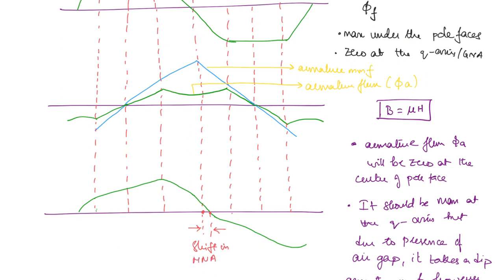So this is the resultant flux. If you take the resultant MMF, it is going to go further up high, something like this, because it is not dependent on the material. So this green color is the resultant flux and this blue color is the resultant MMF. So note the difference.